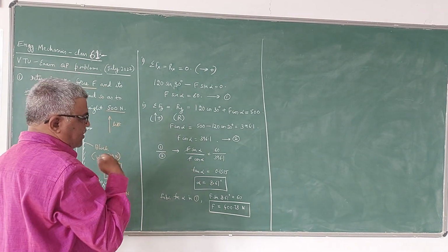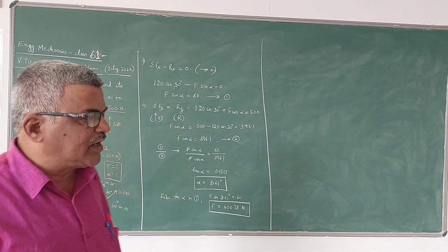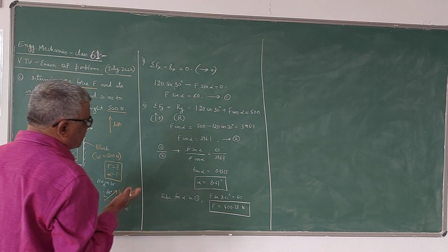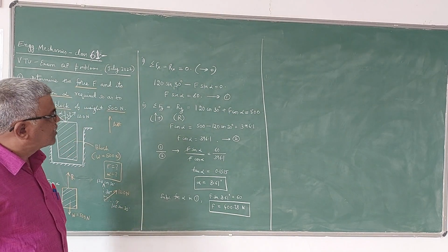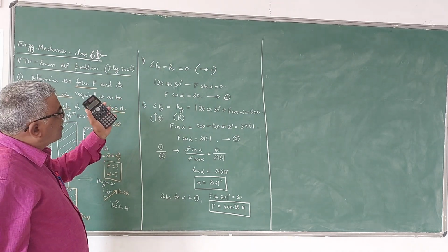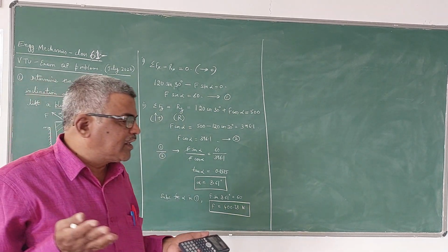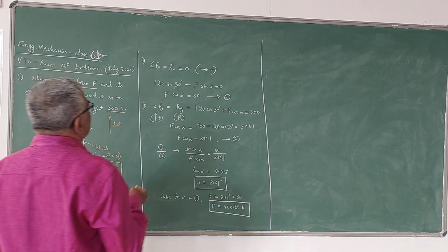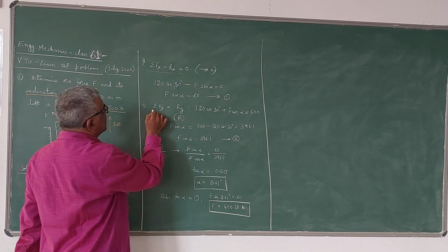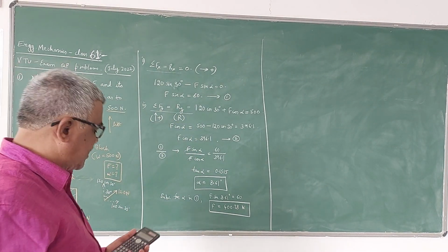Whenever the direction of the resultant is fixed and its magnitude is fixed, then definitely you can find the values of the unknowns, force and angle, by using the equations of equilibrium, that is by equating sigma Fx to the x component of the resultant, and by equating sigma Fy to the y component of the resultant, you can find the required unknowns.